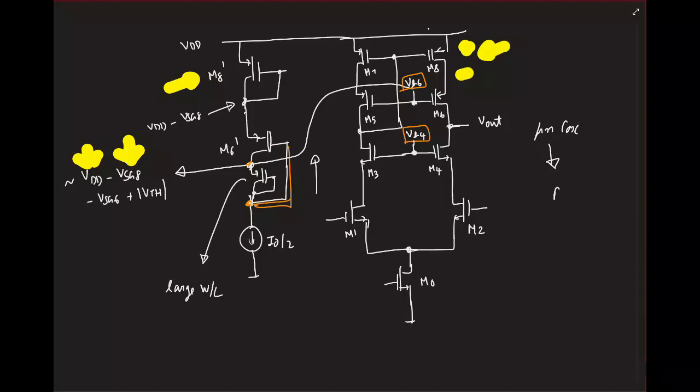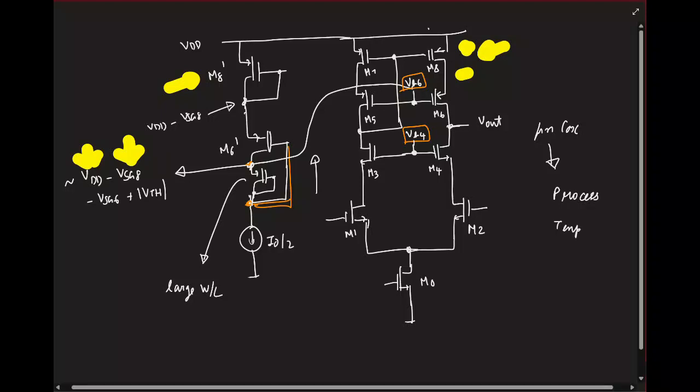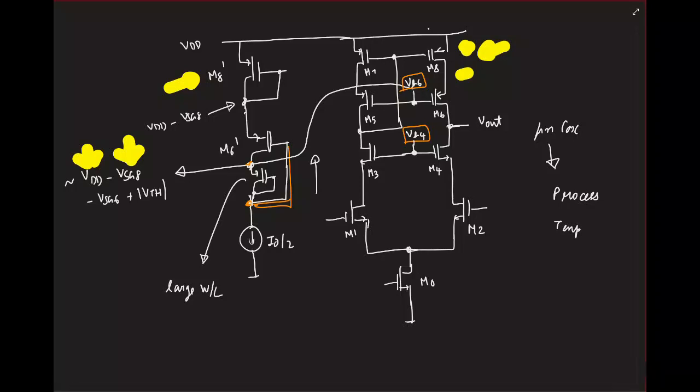We'll look at it later. It's called process variation, so a single calculated value will not work. Plus, it will vary with temperature also. On exams, yeah, you can find nice round values and put them in, but it doesn't work in practice. So we'll have to have some tracking circuits like this that will generate the required voltages.